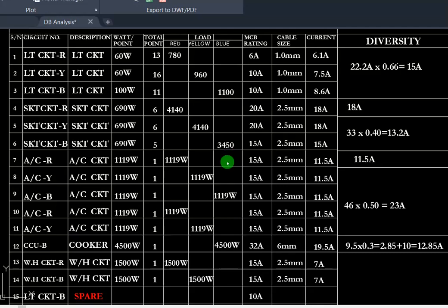So that I will save you the stress of going to the ground floor and first floor to plot this table again, we're going to use this table and use the load we got from here, and multiply it by 2, so that we accomplish our load demand at once. All right, so let me walk you through how to apply the diversity factor.